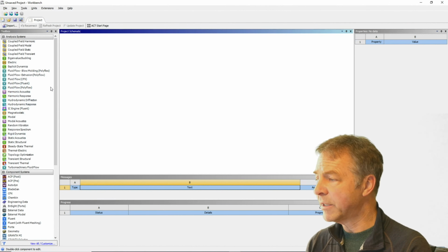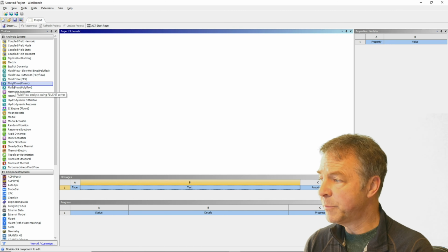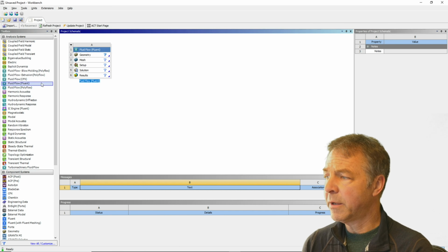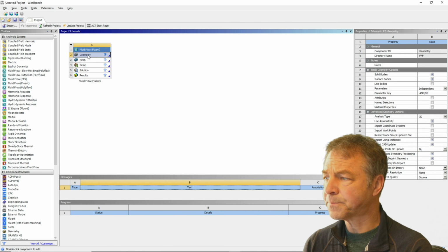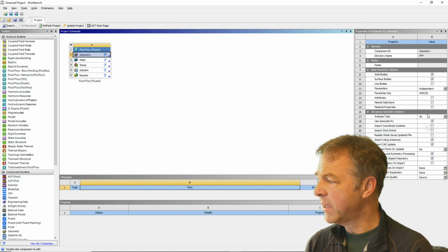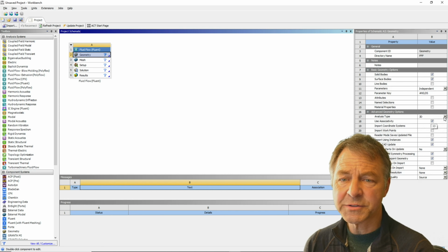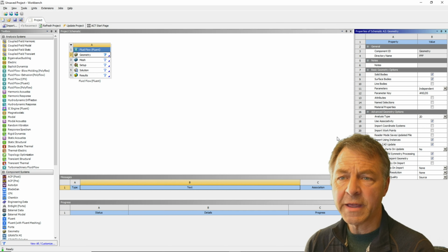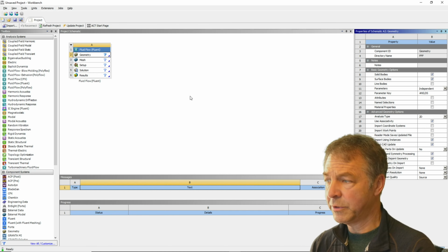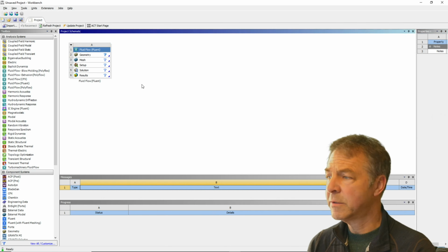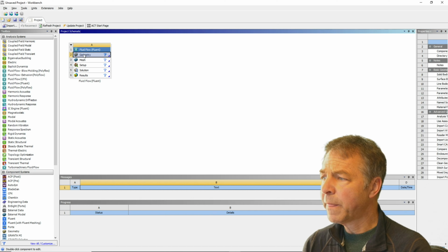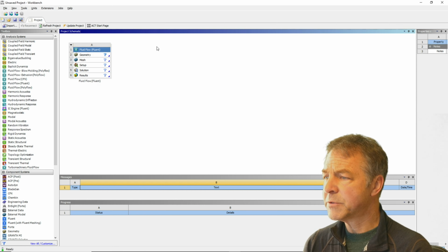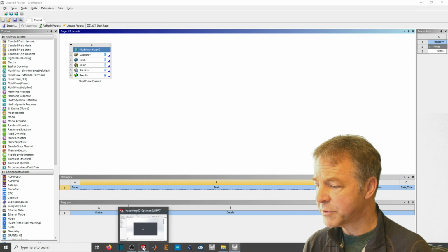So now I'm starting fresh, and I want to do a two-dimensional wing analysis, similar to what we did in SolidWorks. And I create a Fluent standalone. Geometry-wise, the first thing, and fundamentally important before you do anything else, is go down here and select two-dimensional. If you've done that, then everything else will be reasonably okay. So we'll just leave that. Now, we don't want to use SpaceClaim, so I'm going to import geometry from SolidWorks.